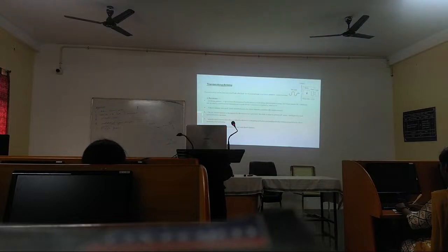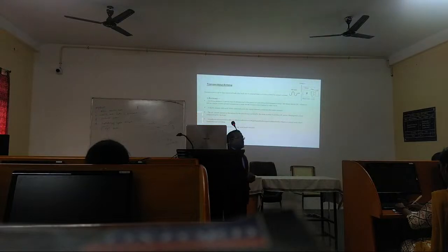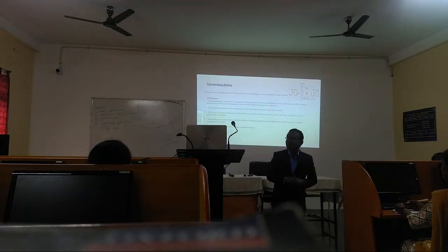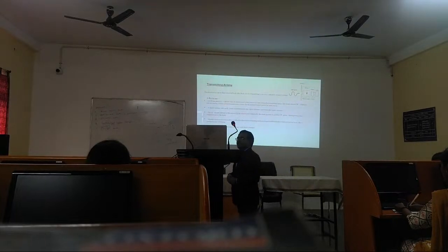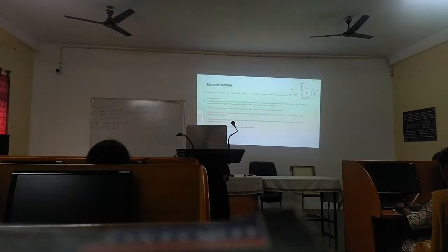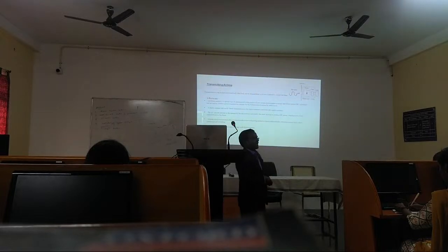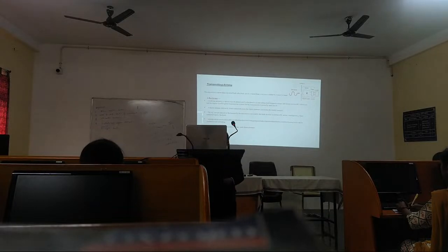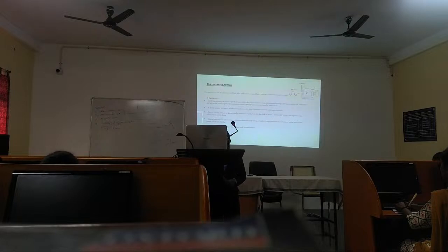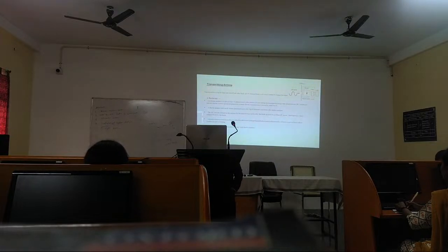Okay. A dipole antenna with a radio frequency diode connected across the dipole element constitutes the simple rectenna. One simple rectenna element consists of a dipole along with one Schottky diode with a filter. The filter takes care of any ripples to give pure DC. Okay, and the load is connected to the output of the antenna. Fine. The AC current induced in the antenna by microwaves is rectified by the diode in order to produce DC power, which powers a load connected across the diode.